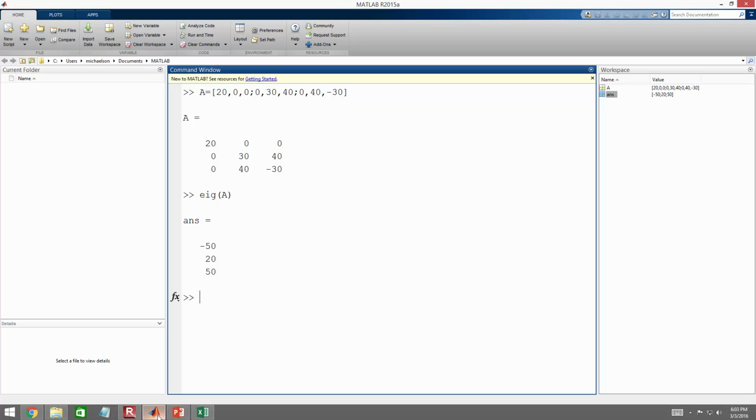If you take the G string or an E string or a B string on a guitar and you play it really lightly, or you wail on it, the sound may sound a little rougher, but it's the same note. It's the same tone. It's because that string has the same mass, the same length, the same stiffness, and when it's vibrating freely under its own free will, it will vibrate at the same frequency every time, okay? That's what a natural frequency is.